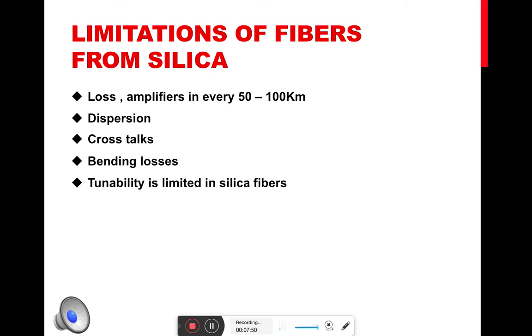Tunability is a factor that is related to the index, that is, the refractive index. So when the fiber is being designed, we have to consider the tunability of the fiber. When we are using silica fiber, there are limitations in the tunability of silica fibers. Because of these limitations of silica fiber, we are going to another type of fiber, that is photonic crystal fiber, PCF.